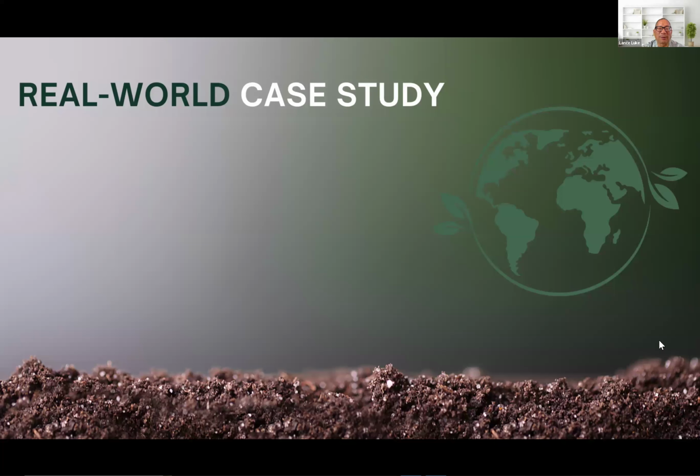So the design of that high-rise building, they didn't put their footings, their piles, all the way to hit bedrock. It was short. And that's the reason why the building was sinking, because there was no stability. I think they went down 100 to 150 feet, but bedrock is like 300 to 400 feet.